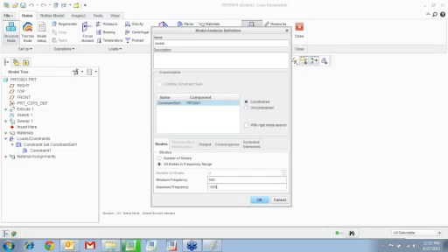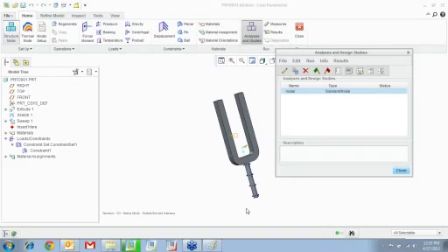So it's going to find out the natural frequencies and tell you, hey, there is a possibility of your machine's natural frequency matching with the bridge's natural frequency. If that happens, then everything's going to vibrate because of resonance, and then the bridge might collapse. So you can find it within a range, or you can go, hey, just tell me what are the first 4 natural frequencies. All right, so you can do that.